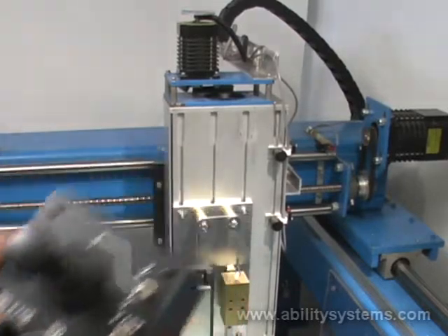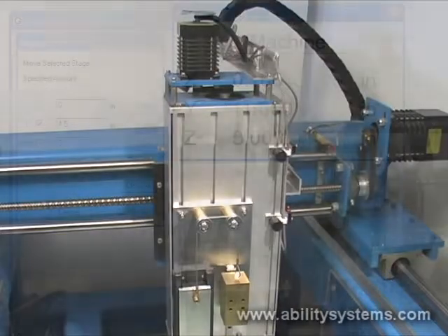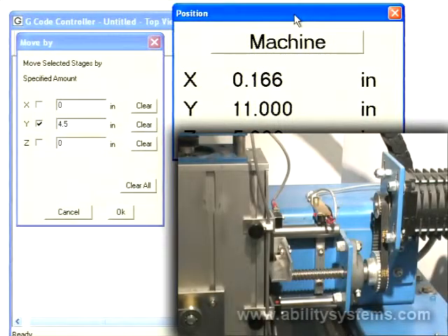The point that is emphasized here is to demonstrate controlled stopping and position tracking. Later, we'll see how it enables G-code controller to accomplish things like locating fixture offsets, sensing a homing plate, measuring and assigning values for tool length compensation, and recovering from tool breakage. So far, we've only discussed controlled stopping.